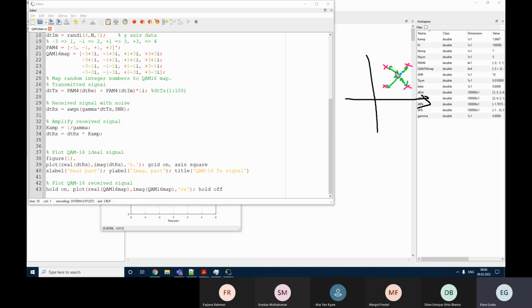Well, of course, we assume that noise is not too strong, yes? So that means that originally we were sending this symbol, but because of the noise, this symbol has moved a little bit, yes? And naturally, if the noise is not very ridiculously high, this movement, this displacement will not be large, and it still will belong to this sector, to this area of the symbol. Yes, we can mark these symbol areas, and it should be considered as this symbol during the detection process.